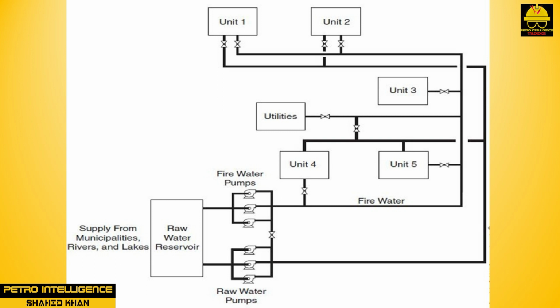Raw water is supplied to the units in the plant by pumps. All pumps can be remotely started from a utilities unit control service. Normally, 1 or 2 pumps are in operation to maintain 125 to 150 psi pressure on the RW system. All raw water lines are located above grade.